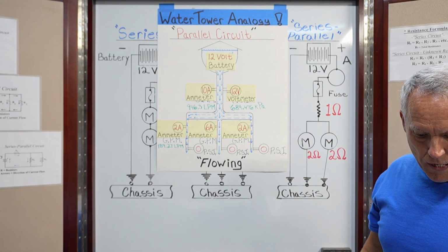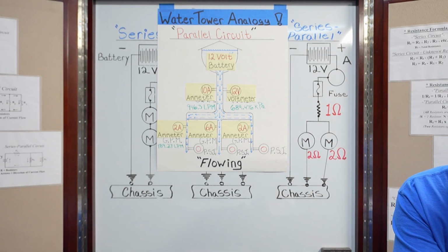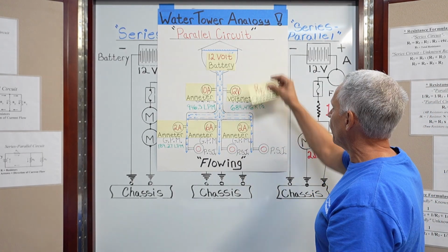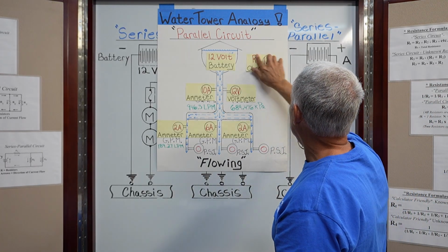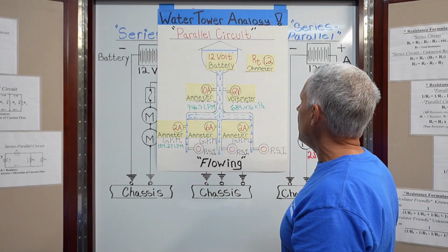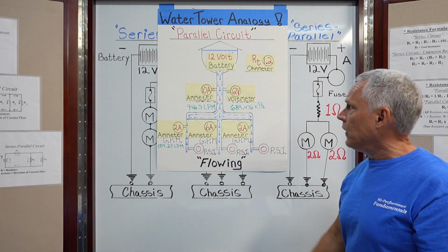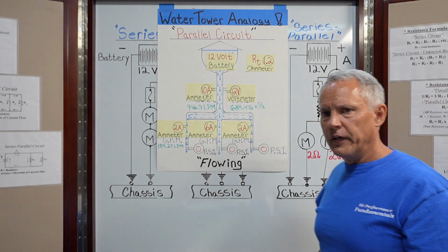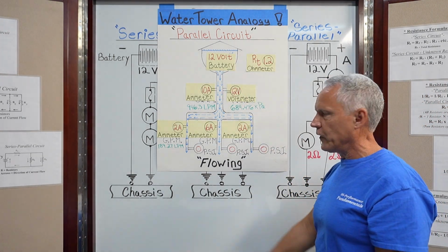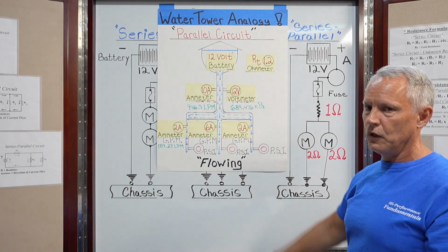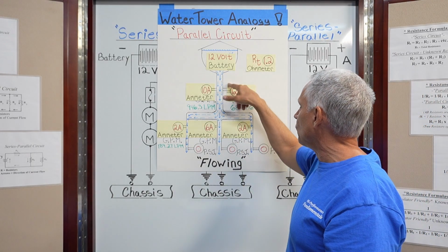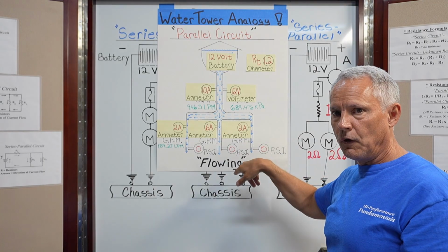All right. Now we want to figure out resistance. So say the total resistance in the circuit is 1.2 ohms. We're having an ohm meter and we're checking the resistance through the circuit. Let me make one notation for you. You never use an ohm meter in a live circuit, right? If this circuit was live and flowing current through it, I would not hook my ohm meter to it. You can damage the ohm meter. Don't do that. So do not use your ohm meter through a live circuit, okay?